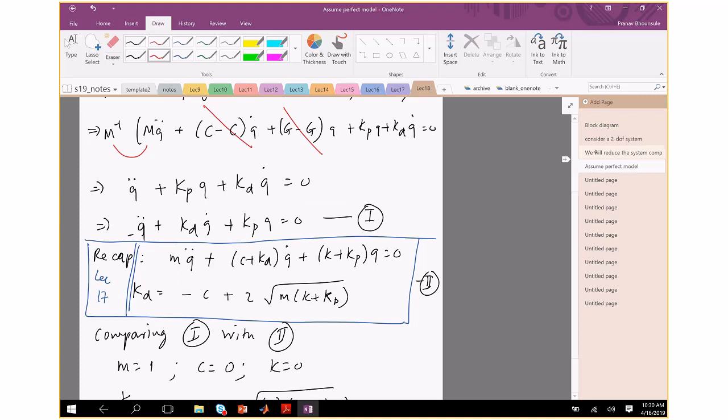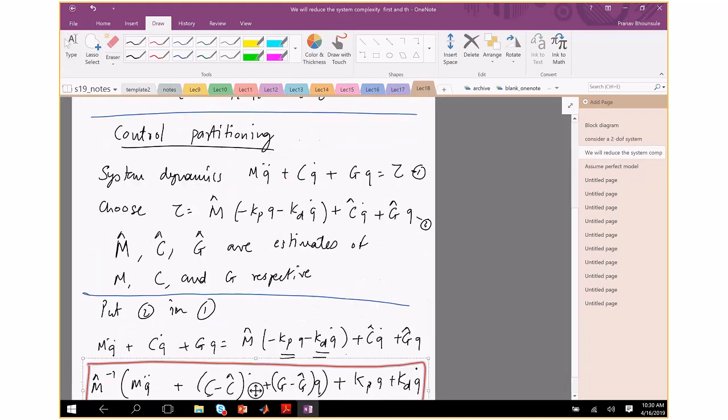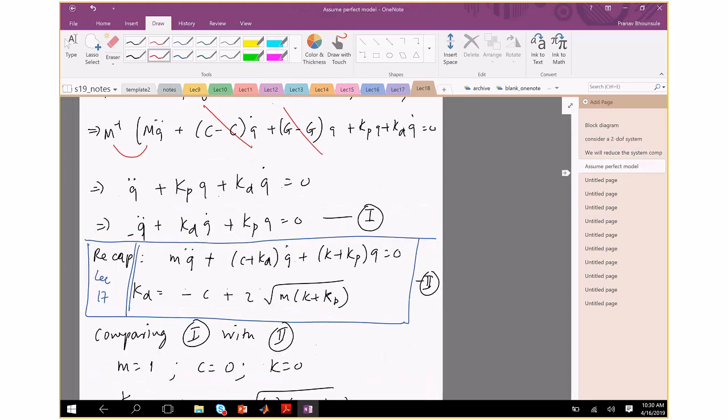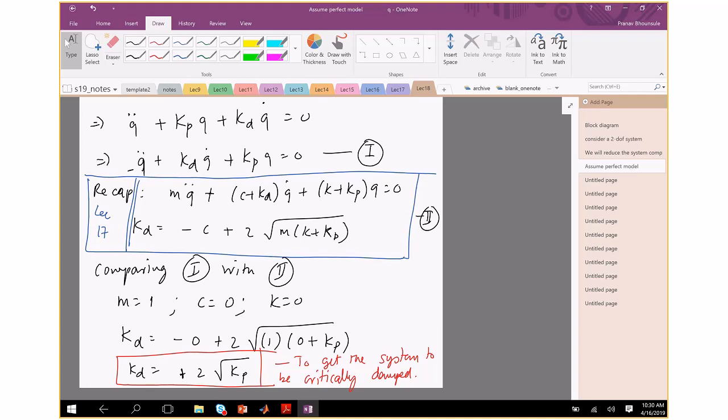you also need to choose the torque in this fashion, right? Provided you choose torque in this fashion, where the K_P and K_D relation is found, you will get the system to be critically damped. In fact, it's much simpler. It's basically writing n equations, each of them independent of each other. When I saw this first, it was really hard to understand, but you should read this once or twice and you'll get the gist of it. It's really playing with the math, and there is a physical meaning to how it's done, but you want to repeat this yourself to understand the math.